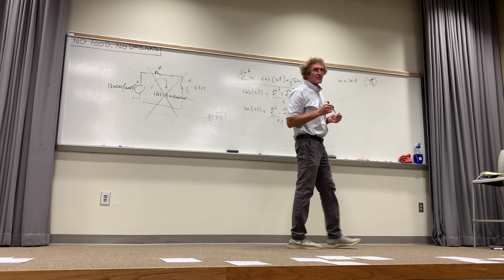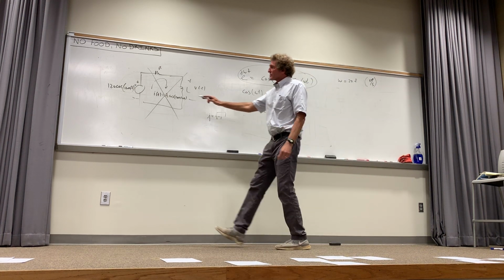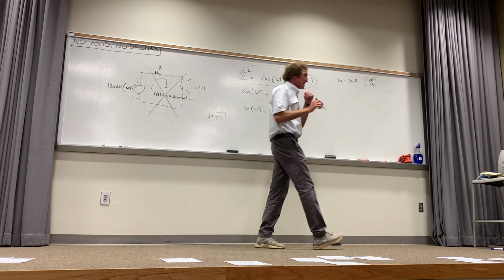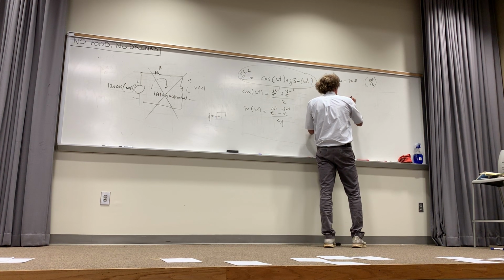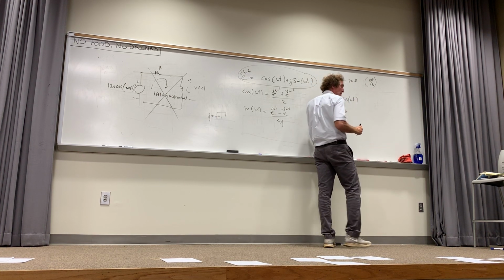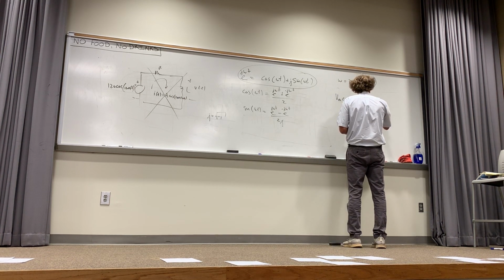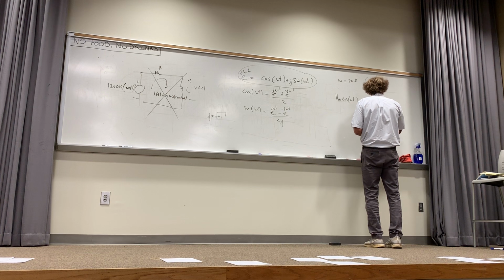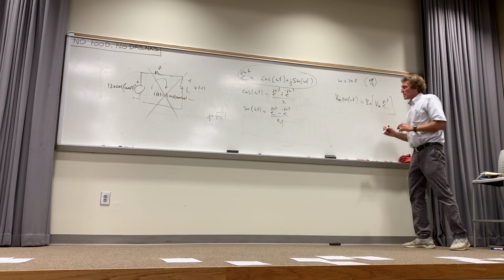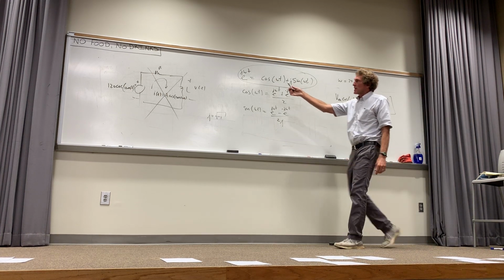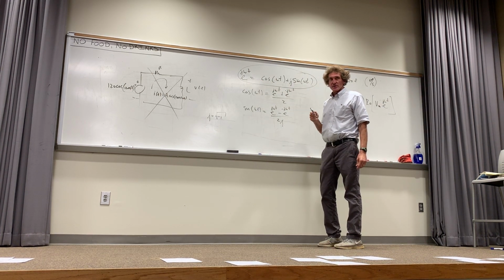And I'll show you one thing. We are not going to solve something like this. What we're going to do is say this, that I know that Vm times cosine of omega t is really equal to the real part of Vm times e to the j omega t. Now, if you look at what I've done, if that's e to the j omega t, this is the real part, that is the imaginary part, because its coefficient is j.